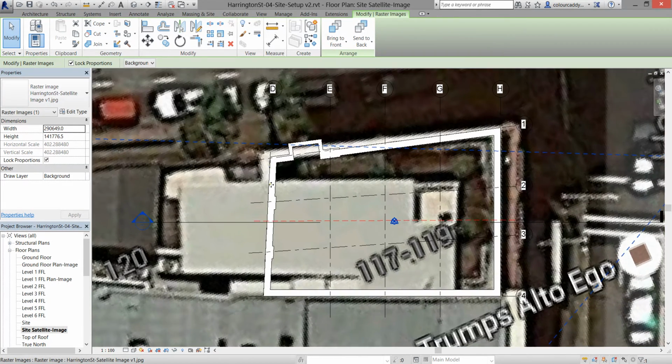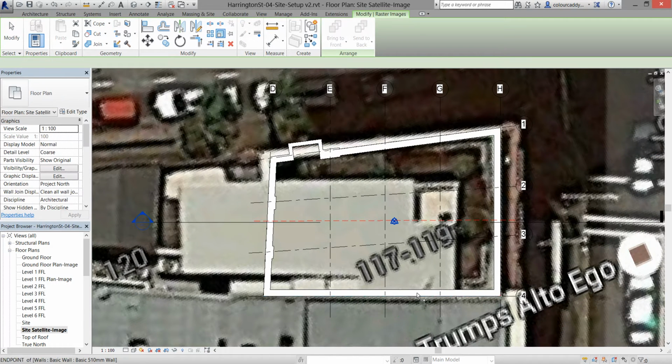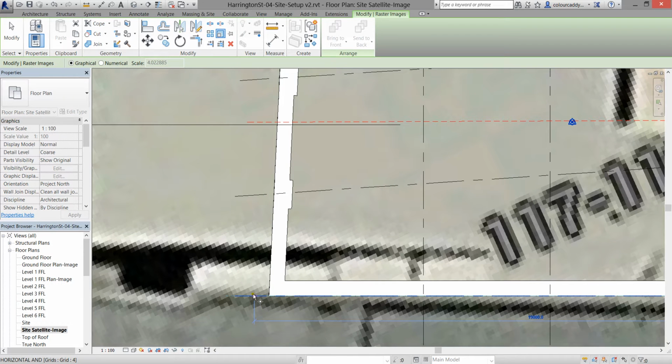Close enough. You can always maybe that's I think the corner of the building in reality. So if you want to scale it back down a little bit, it's not a bad thing to try. Just going to click on Scale. Again, starting on this corner. So it's come out a little bit too far. We can't actually see that corner, but that's okay. I'm going to just guess. So it's about there, and now bring it back to here.